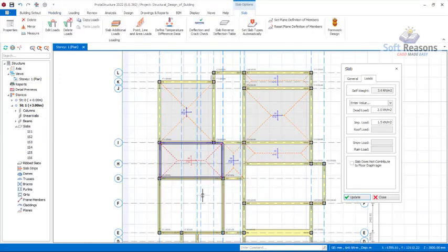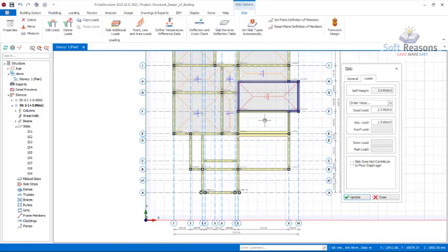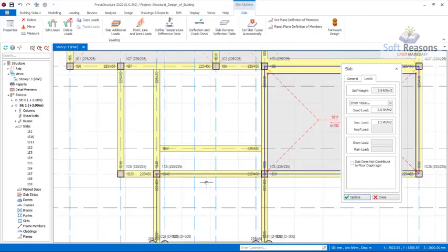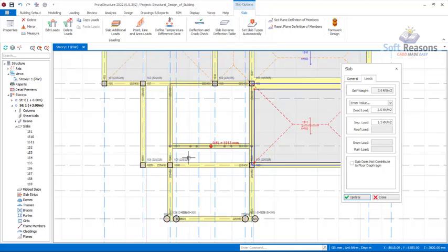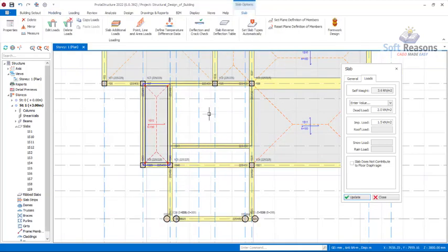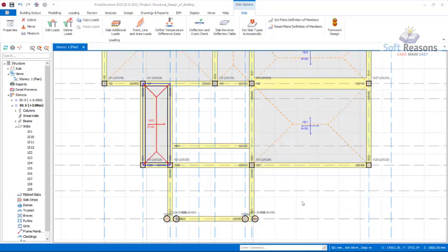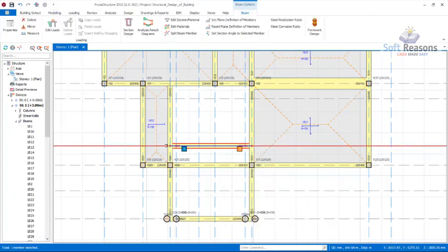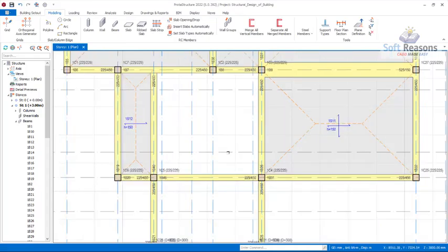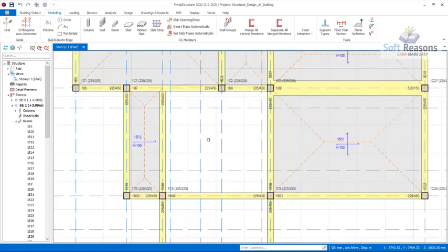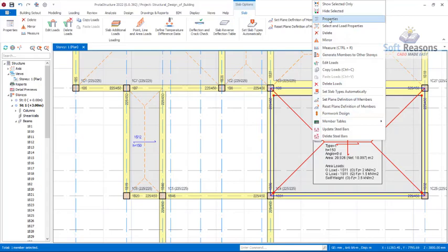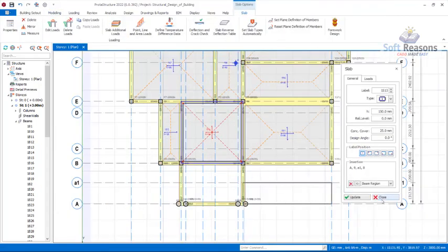So we leave this provision open because it's for the staircase. Alright, so in this, we may not necessarily get this beam here. Let's place a slab here. We'll remove this beam here, because having a double beam here is not cost effective. So click on the close options. Let's remove this beam, and I will run a wall load there. I will show you how to do that instead of having a beam, because this area is not up to 30%.